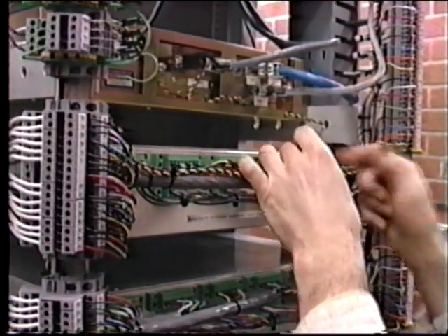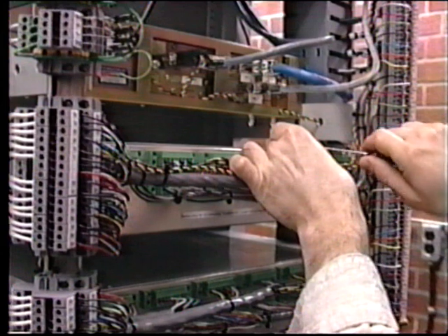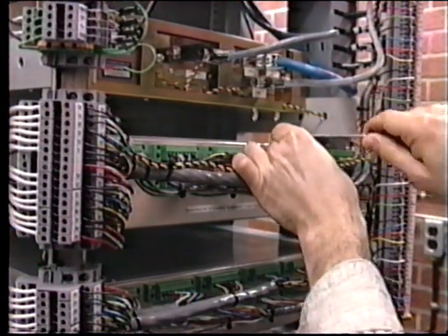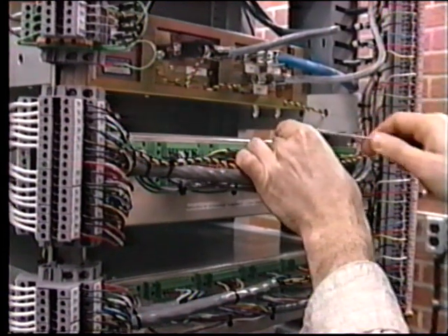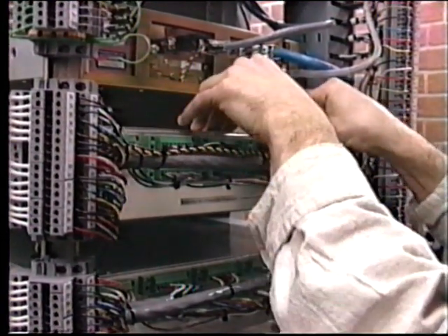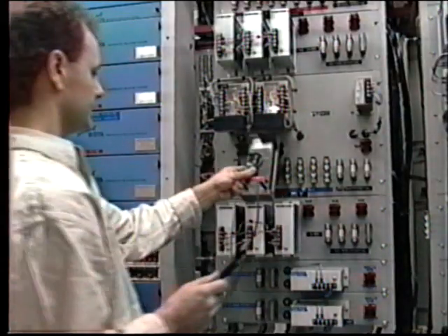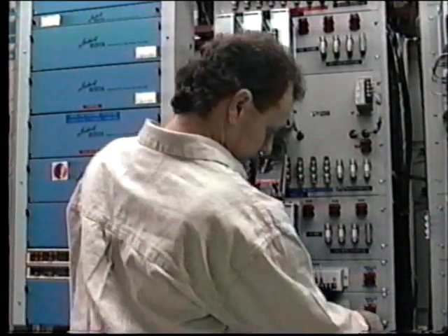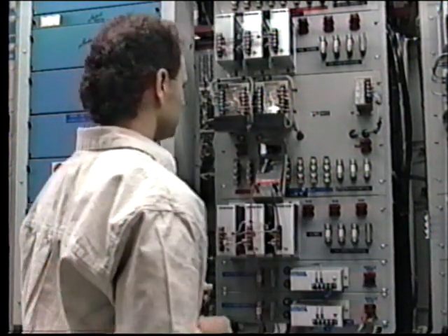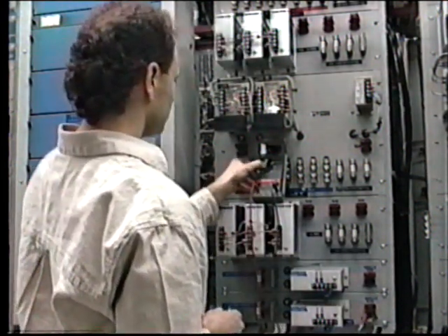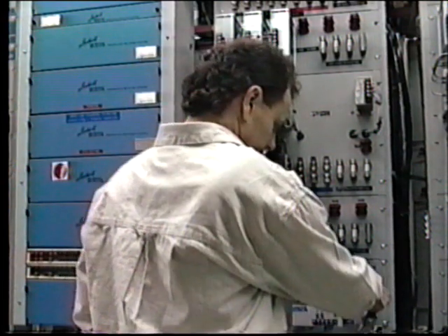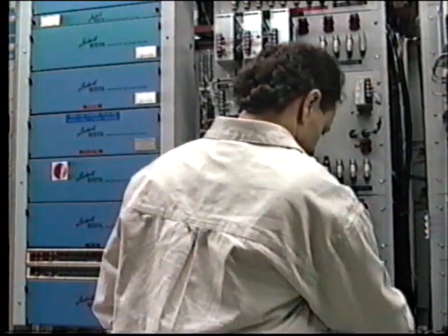Preventive maintenance generally consists of regular inspection for cleanliness, terminal board connections, and climate control. The power supply should also be checked to ensure that it really is uninterruptible. Also, at regular intervals, the telemetering measuring points should be checked and the transducers calibrated as necessary. When doing this, don't forget to check CTs and VTs and refer to error characteristics.